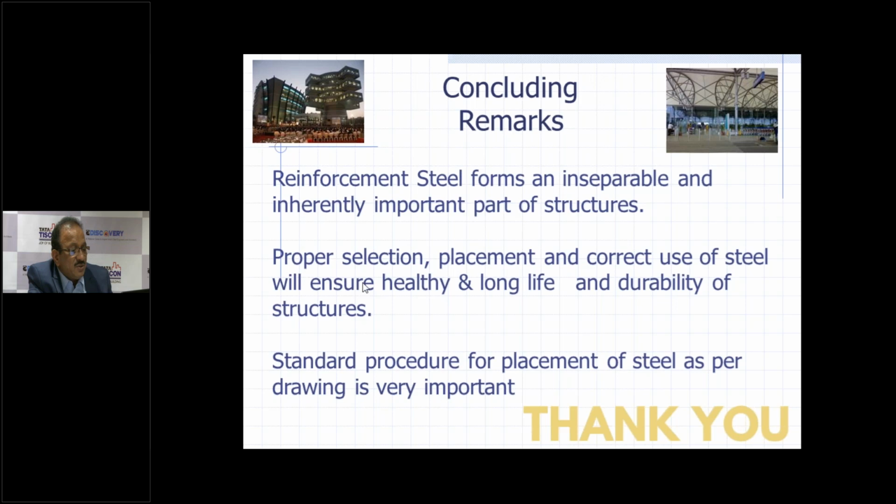Last 2 questions. Pushkar Patel wants to know, can we weld the bars instead of couplers? No, I will not recommend welding of the bars, because welding reduces the strength, and couplers can guarantee you the efficiency of the joint. In a particular column, if there are some 40-50 bars, welding each bar efficiently is very difficult to control in quality and efficiency. So welding can be a risky solution, but couplers are a 100% foolproof solution.